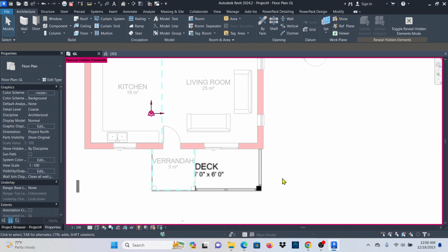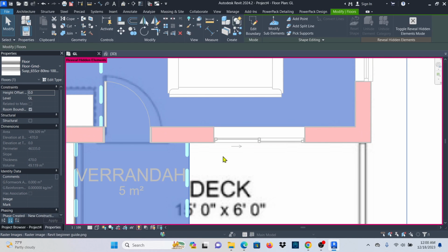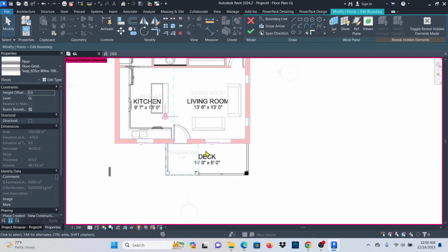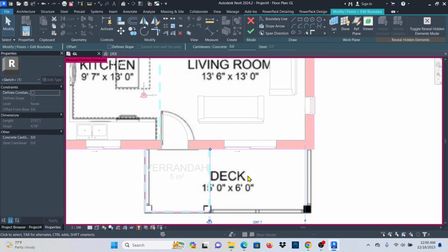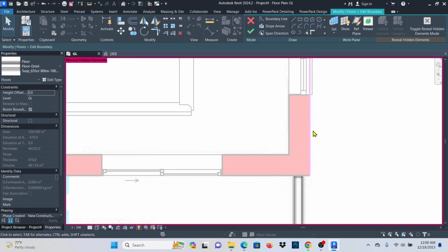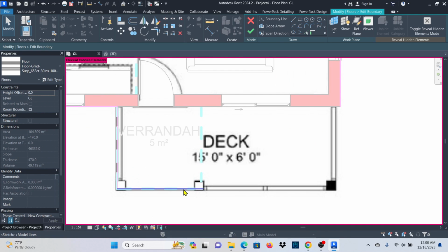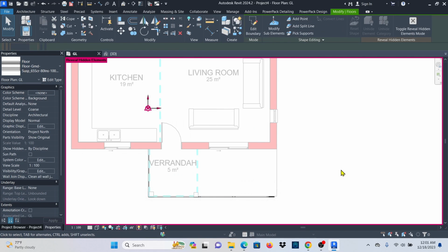Now what I'll do is to simply edit the floor, I think, so let me hover my cursor there, then select the floor there and click on edit. All right, is this the floor? Yes, then I can select on that one and hold control, select on this one, then I'll delete it. Then we have this line and this line. I'm going to trim, TR on your keyboard, pick this one and that one, then click on finish.